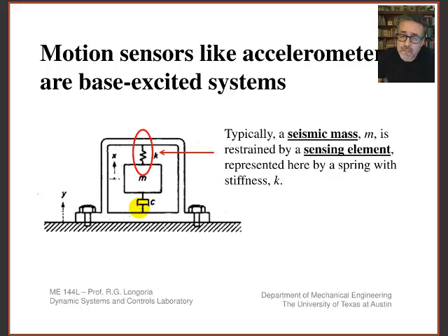And actually, sometimes in accelerometers, they will intentionally put damping in there because you want to control the dynamic characteristics of these devices so they have favorable performance. Sometimes they fill them with fluid or another type of damping material in order to make them perform a certain way. And from your understanding of mass spring damper systems, you understand how you can control the damping level with that C here, or B, the damping coefficient.